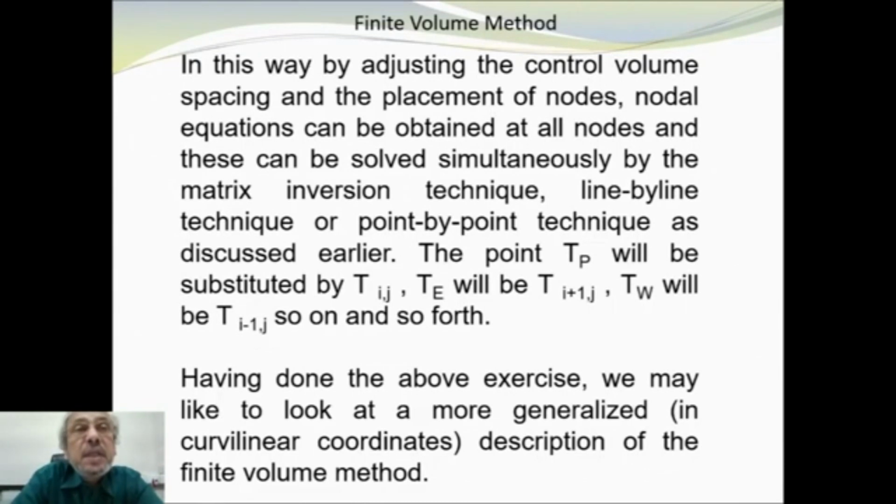While expressing, if the neighbors are represented by their node number, then they will come straight away. If the neighbors are represented by a boundary condition, then we'll adopt the boundary condition. That means while formulating the problem, the nodes neighboring the boundary are to be paid special attention, and then we'll be able to get the